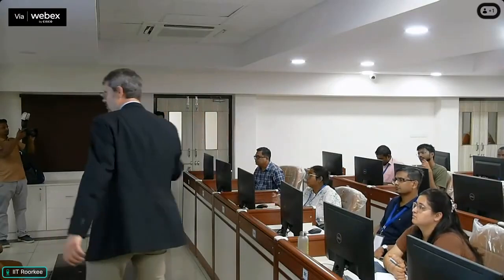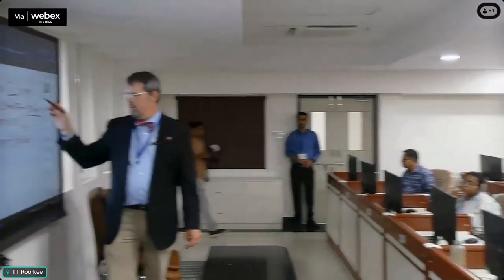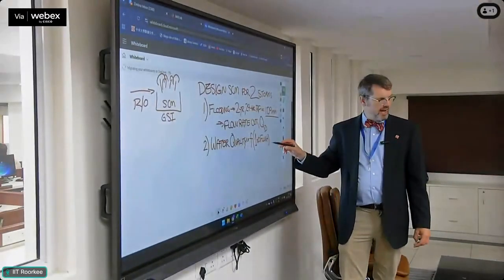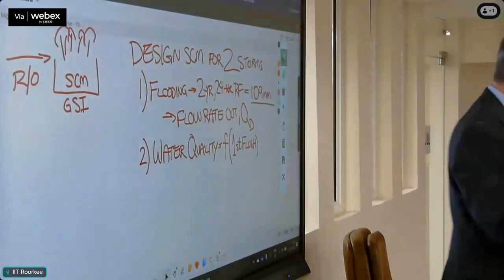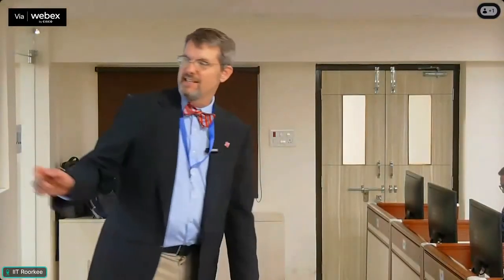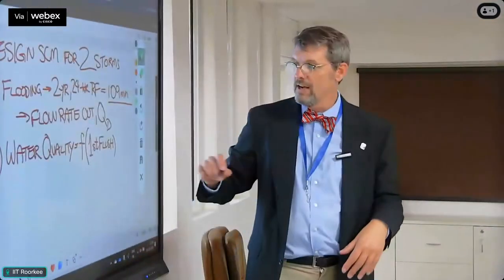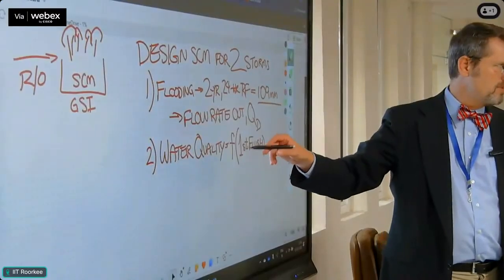Okay, great. And so knowing that the water quality storm is associated with the first flush, and knowing that the first flush favors more pollutant loads for smaller events, and it's cumulative over the course of a year, this is necessarily going to be a smaller storm size.